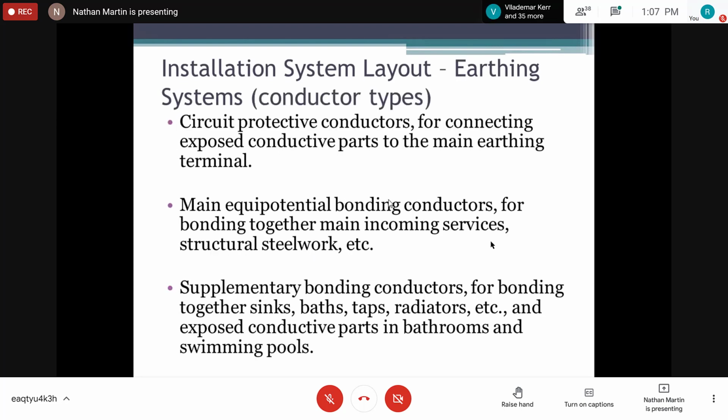Now, conductor types used to earth. If you are talking about your service conductor, we also can calculate the size of your earth, right? Typically, what electricians or engineers or technicians will do is to size the earth conductor of similar size as the phase conductor, and that will take care of any calculation, right?